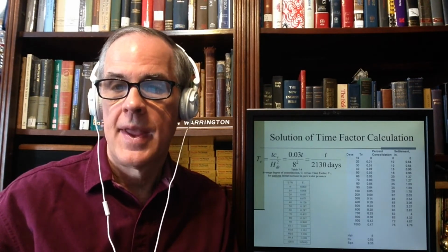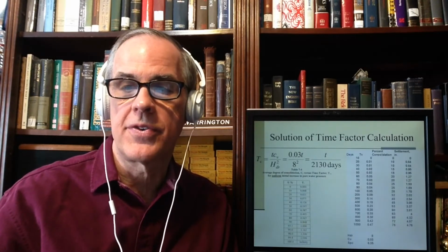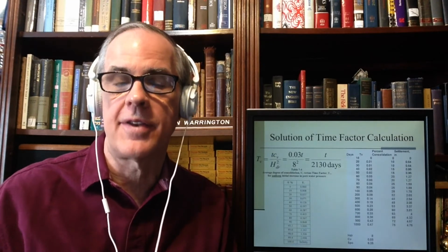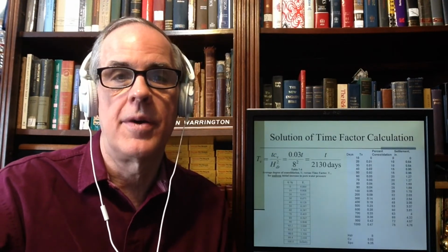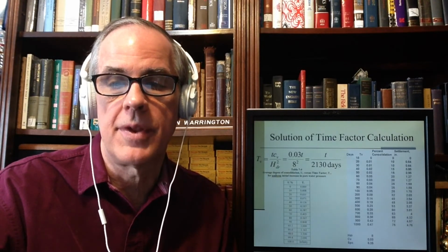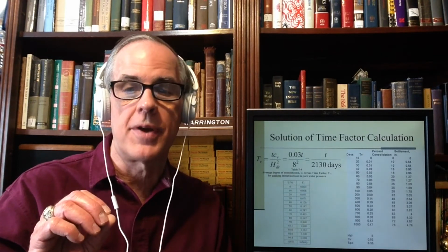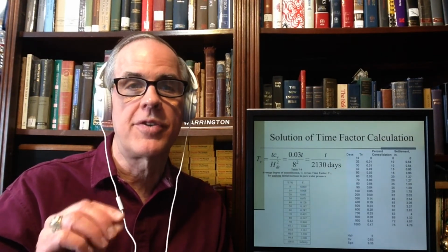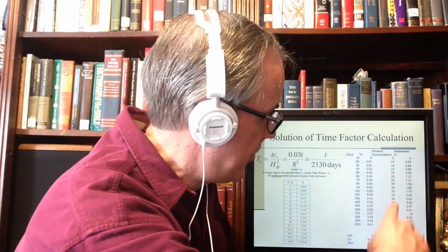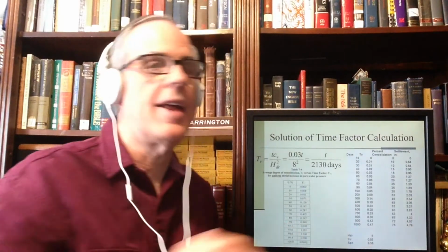And then I get settlement. So therefore, after 1,000 days, for example, I am settled 4.76 inches because I'm at 75% consolidation. If you recall this problem, my original primary consolidation settlement is 6.35 inches, times 0.75 is equal to 4.76. I simply am taking this times this to get that, in other words.